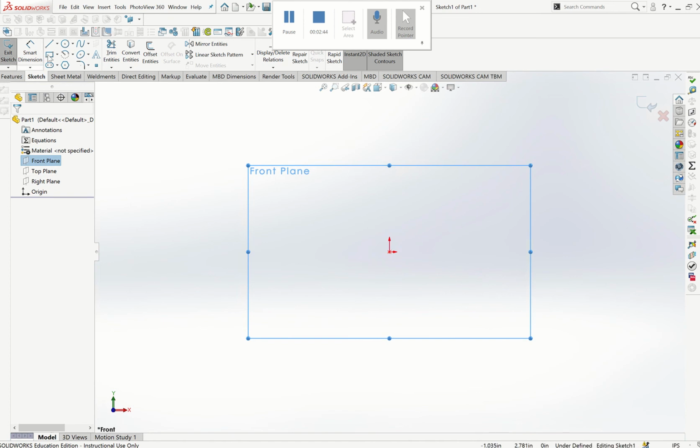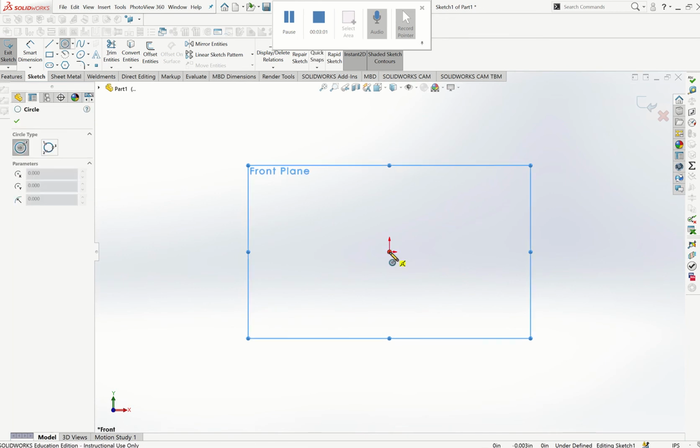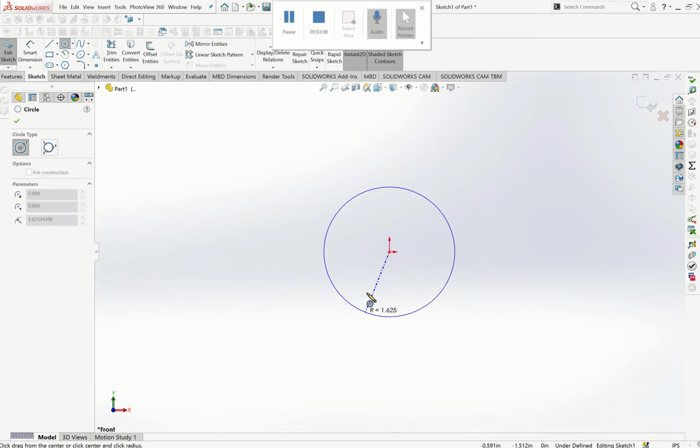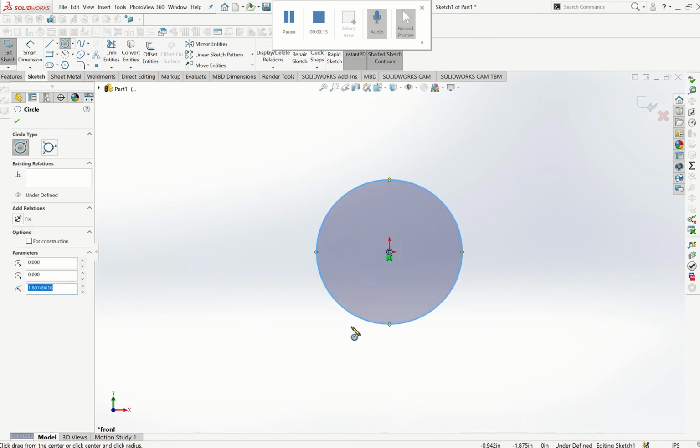For example, I'm going to draw a circle. I'm in the sketch tab. Sketch is going to be 2-dimension, and feature is going to become 3-dimension. You will see that very soon. So we're going to sketch a circle. The center is going to be at the origin. I'm going to left click and just let my mouse toggle, and that shows different radii. Then I left click again. That's where I decided to draw my circle.